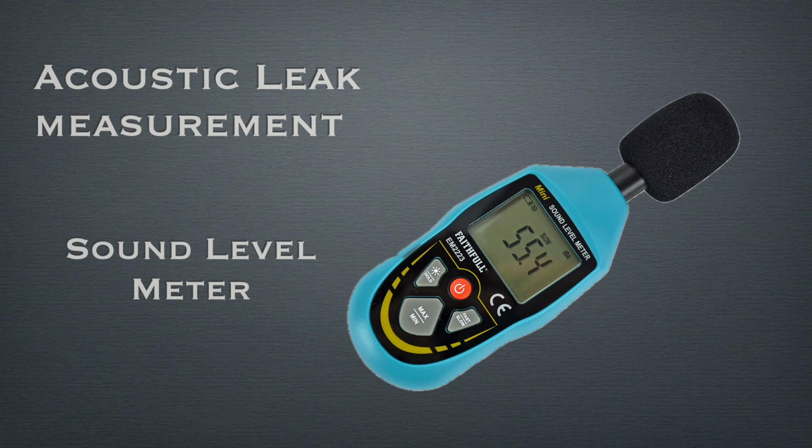So the sound level meter is needed for checking the level of sound leakage from a meeting room. This issue will also be discussed later in more detail, but in general, we use a pre-recorded sound that imitates the sound level of a meeting, place it inside the meeting room, and then check what level of sound can be detected outside the room. I will explain it in a more scientific way when we get to the lesson on this type of service.